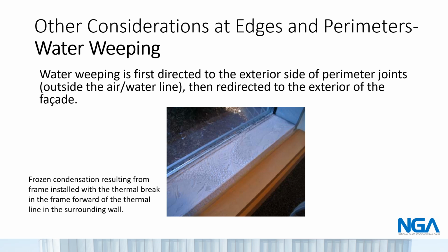Thermal continuity, detailing, and construction must not interfere with any water migration strategies the glazing system uses to redirect any water to the exterior. An expectation that thermal continuity will be 100% through these details at the joint or in the adjacent construction is unrealistic with most present-day glazing systems.